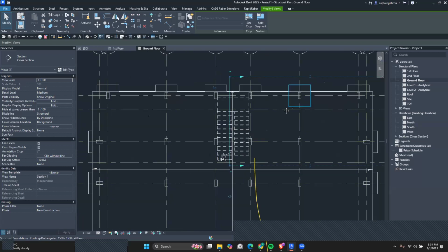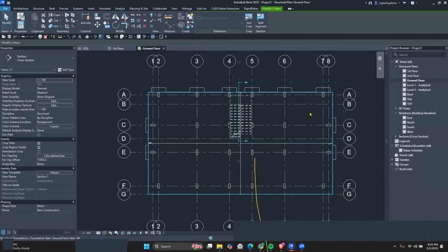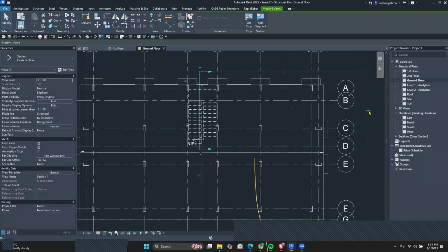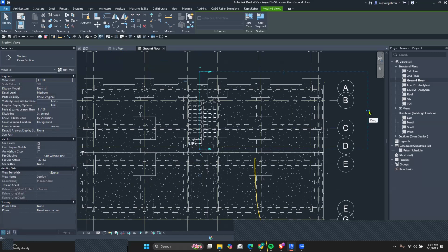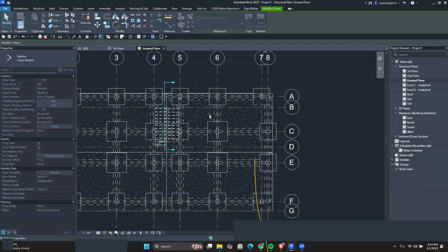And then something else while working with sections in Revit, this dotted blue box with these arrow grips affect the depth that you can see or you can visualize in Revit. So if I was to bring it closer to this part over here, I will only see the staircase. But if I was to extend it further and further, the more I'm able to see.